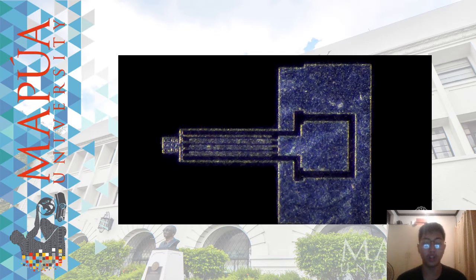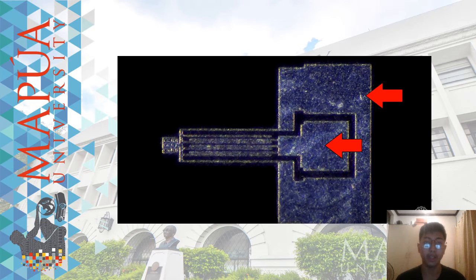Now, in order to understand how an accelerometer works, let's look at a MEMS capacitor. It doesn't look like a capacitor, does it? Well, remember that all a capacitor really is, is two conductive plates that are electrically separated. So here are the two terminals of the capacitor.